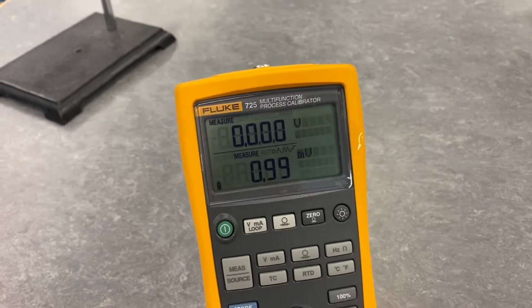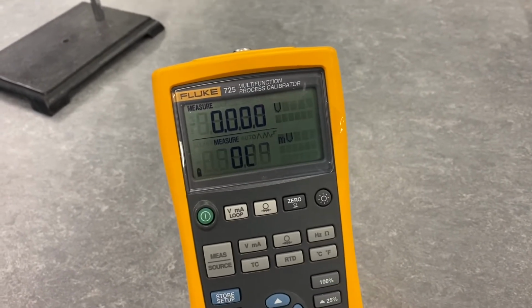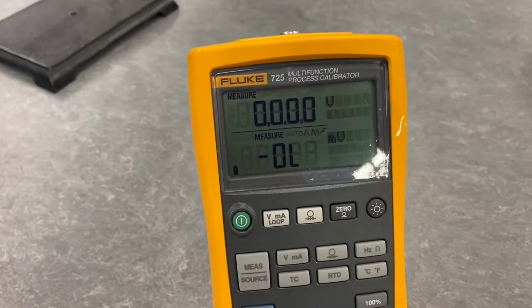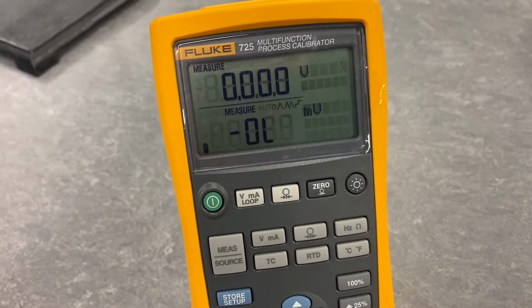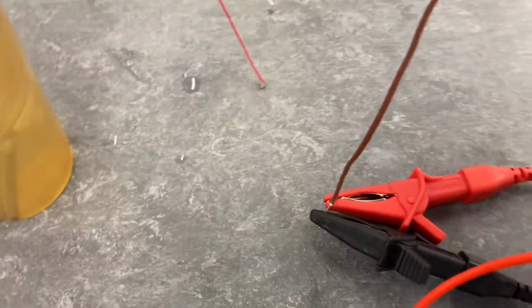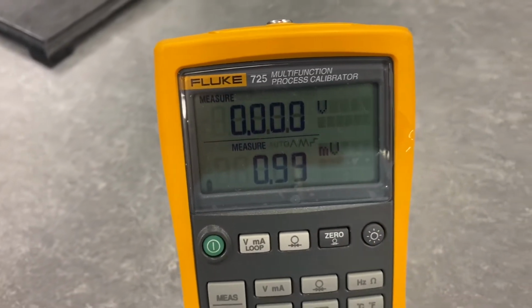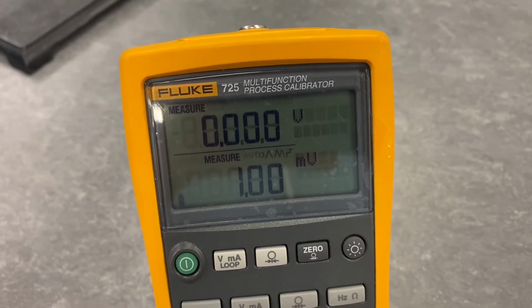I'm not 100%, I might have the polarity backwards here. Yeah, this should probably be a negative voltage. I'll just go ahead and switch the polarity. Positive to the white, negative to the red here. I just switched the polarity. And oh yeah, it's saying a negative overload, because we're reading a negative voltage. We'll just switch the polarity back here. And now it's reversed, and this would actually be a negative almost 1 millivolt, or 0.99 millivolts, there we are, 1 millivolt.